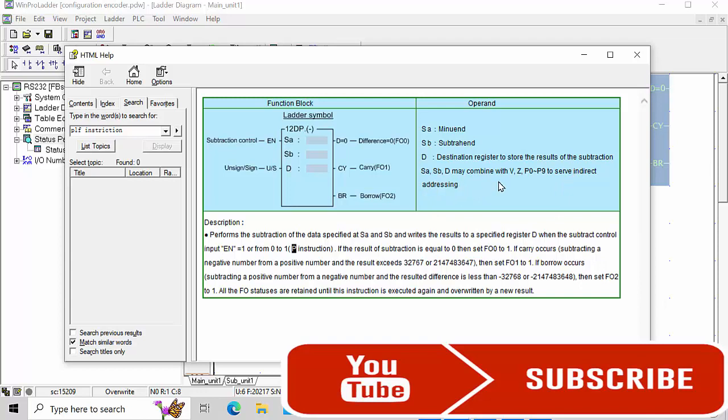SA, SB, D may combine with V, Z, P0 and P0 to P9 to serve indirect addressing. And in the description it says: performs the subtraction of the data specified at SA and SB and writes the result to a specified register in D. Means whichever data you like to write here, and here subtract. After you subtract, you can get the answer in result D.